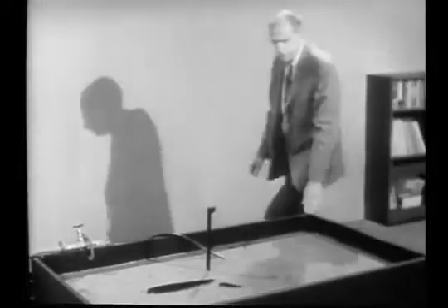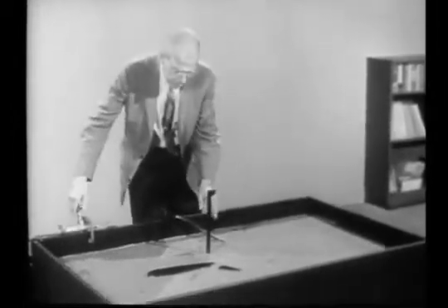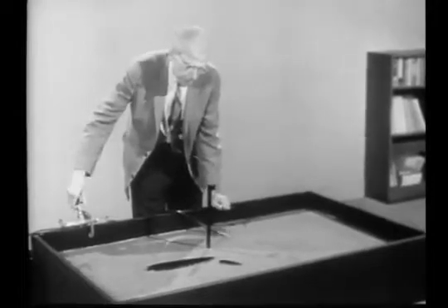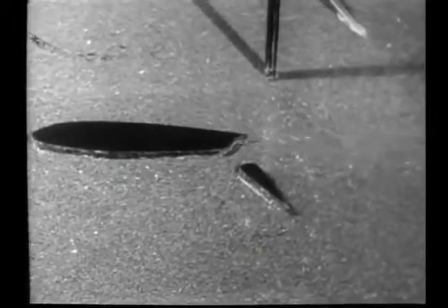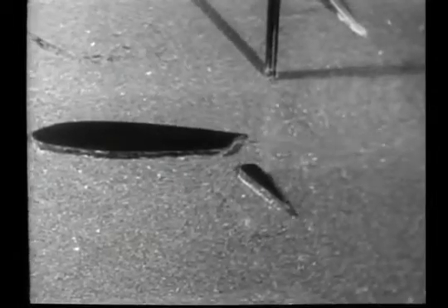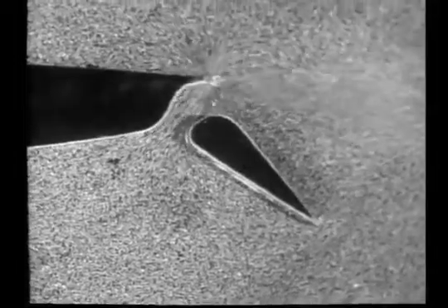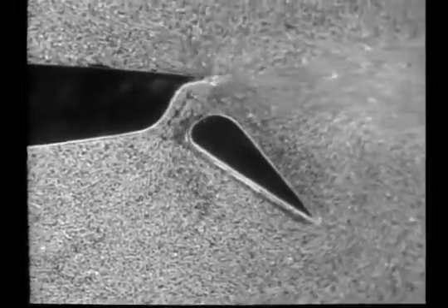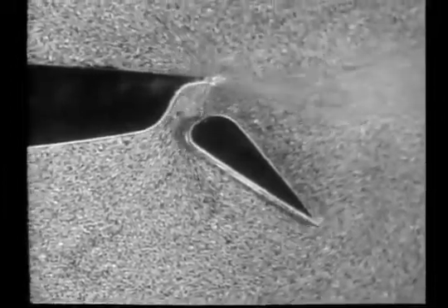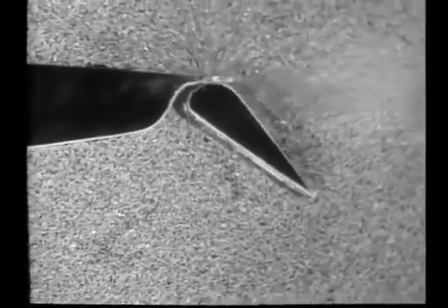Still greater effectiveness can be obtained from blowing jets if they are produced by the direct application of power rather than by the limited differentials available on the body itself. The jet, moving at high speed through the surrounding fluid, creates regions of high viscous stress at its edges, and as a consequence drags substantial amounts of fluid along with it. When such a high-speed jet is near a curved surface, the interaction of the boundary layer with the jet causes it to bend and to adhere to the surface.